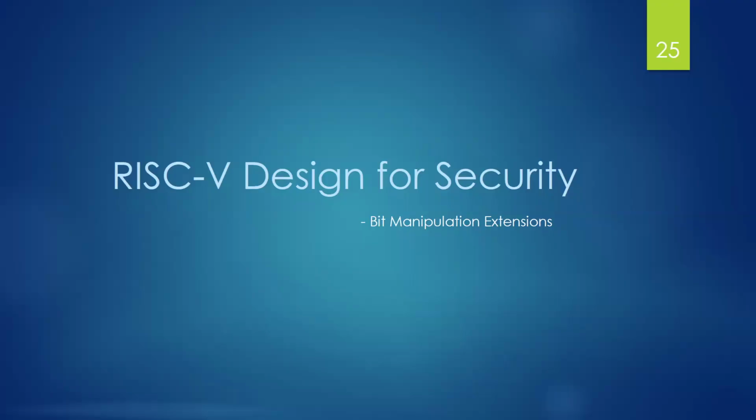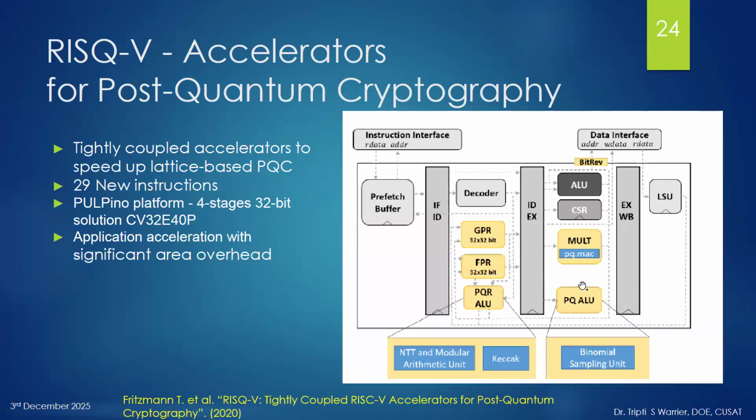But many a times the task will be complex, as a result of which, if you see this diagram, when you introduce something in the execution unit, it will have a delay which is greater than any other component. And we know that in a pipeline, the critical path, the stage which has maximum delay, decides the clock of that pipeline, and automatically it reduces the frequency of operation of the design, and then performance reduces.